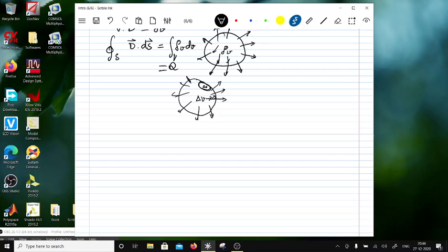So now the component which I do as a curl, curl of H, will be along this loop. Curl of H will be defined as the integral of H tangential dot dl divided by delta S, in the limit delta S tending to 0. Now this is the tangential component of H, and I am talking about